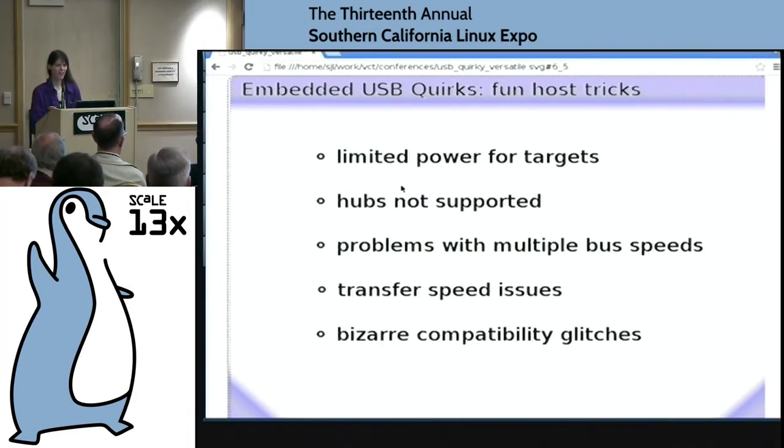And the last category that I've run into is just not really a category I can define. I'll give you an example. This is a real-world example that a couple people in this room will be familiar with. Suppose you have a specialty USB printer. You have it hooked up to a port on your embedded device, and the application is such that somebody turns off power on your embedded device by yanking the power cord. That is not actually that uncommon, right? This isn't a real computer. This is embedded. It's an appliance, so people turn off the power any way they feel like it. Nobody expects to have to do a safe shutdown like on a PC.